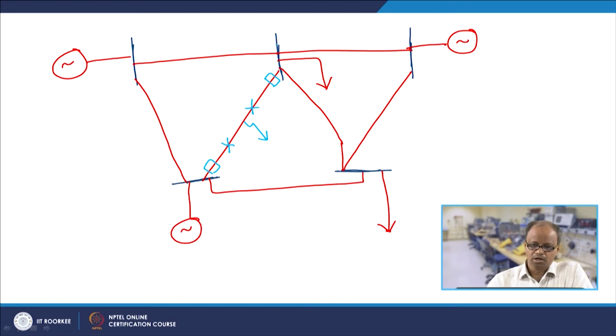And also, because this line is gone, some of the remaining lines in this system will definitely have higher values of current or rather real power flow. So there is a chance that this bus voltage or this bus voltage may go beyond their limits, or through some line the current flow or the power flow, either real or reactive or both, may also go out of their limit.